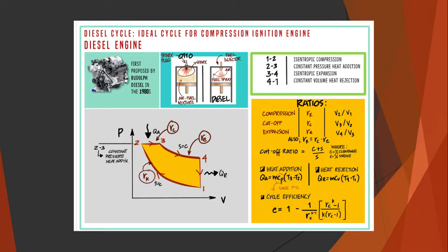Then there is also no heat transfer, because in compression, the gas is compressed adiabatically from state 1 to state 2. In real engines, there are always some inefficiencies that reduce the thermal efficiency. And in expansion, the gas expands adiabatically from state 3 to state 4. Then here also, complete combustion of the mixture. And there is also no pumping work.